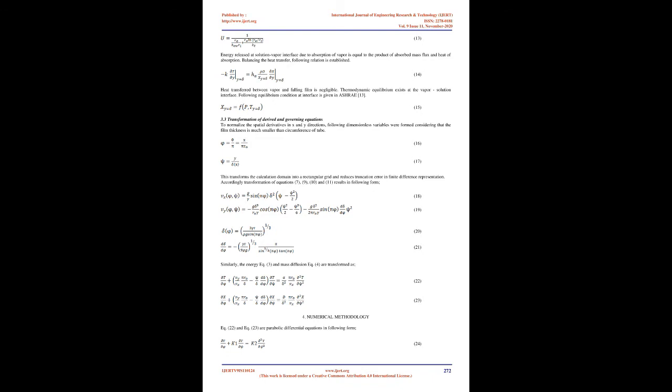3.2 Derived equations. Integrating Equation 2 and determining constants with the following boundary conditions, Equation 6, the velocity profile in the film flow direction is derived as follows. Using continuity Equation 1 and the boundary condition of no shear stress exerted at the interface of solution and vapor, Equation 8, the velocity profile in the film thickness direction is given as Equation 9,